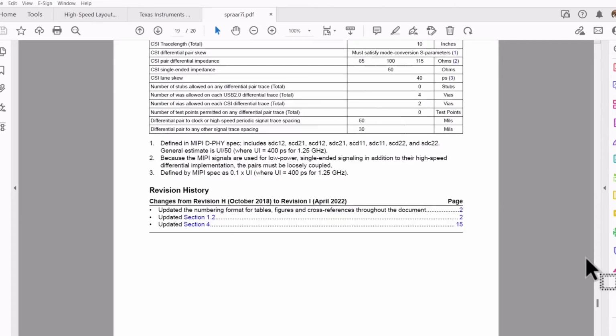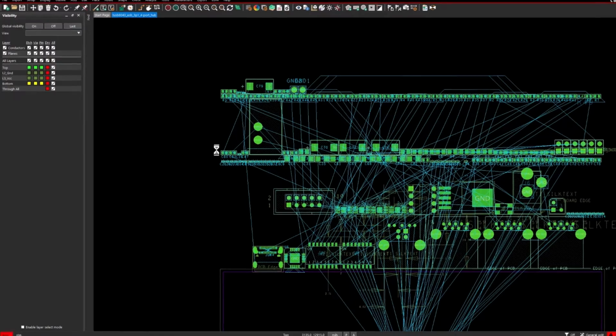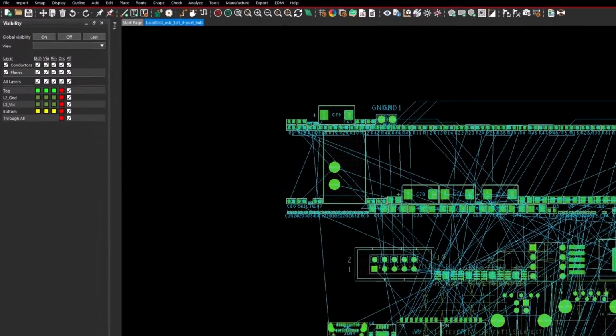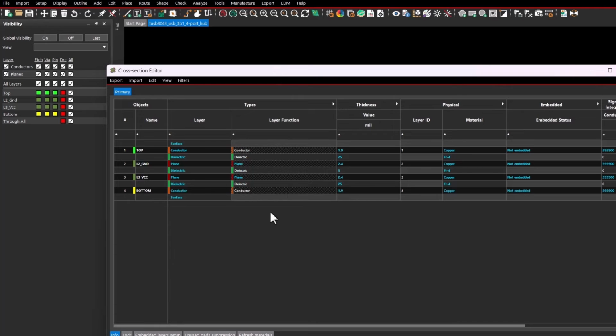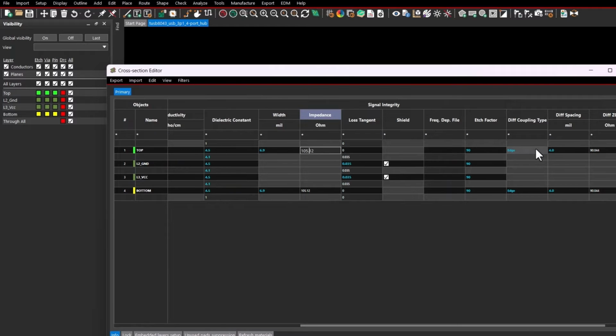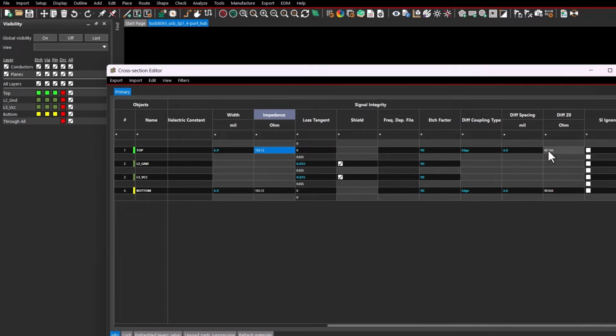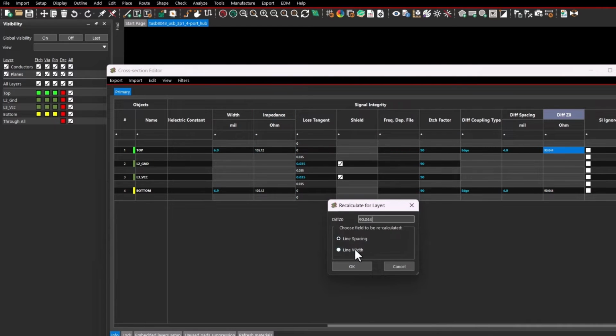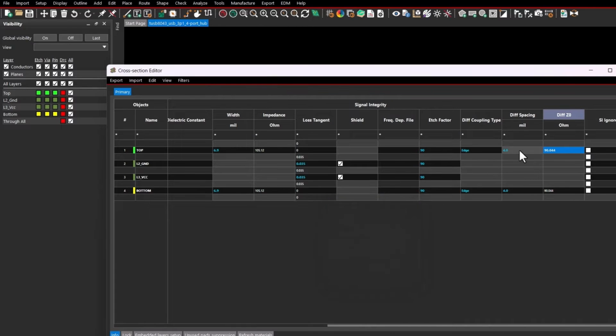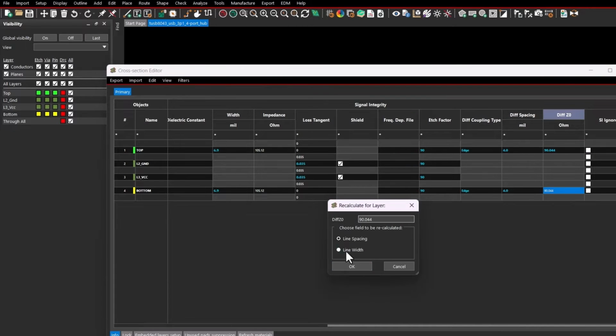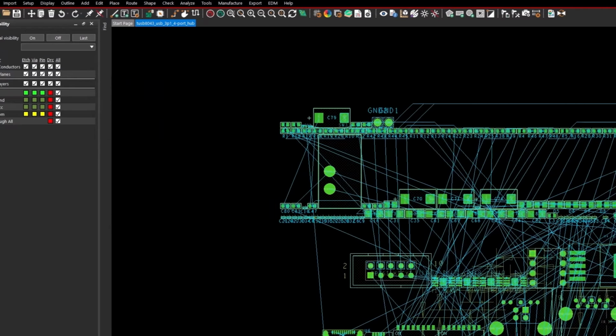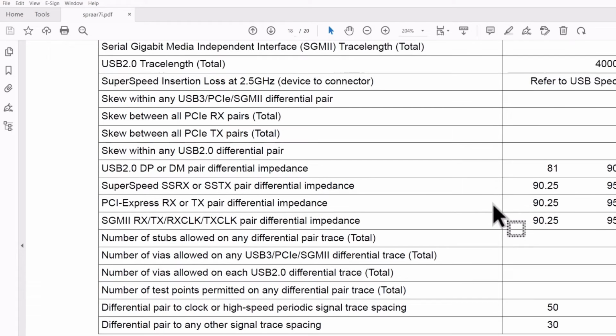So actually the thickness of the PCB, the dielectric layers, and also the copper, they all affect the impedance of your trace. If you want to control the impedance, make sure you have your stack up done first and that the trace widths and the spacing are within manufacturable limits, while also having them meet the recommendations and/or requirements, like for instance what Texas Instruments has here.